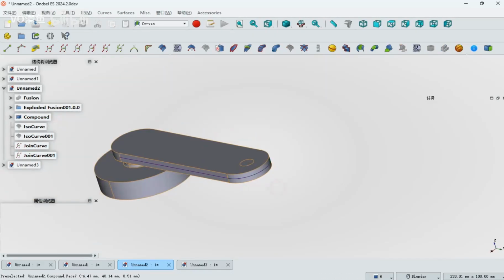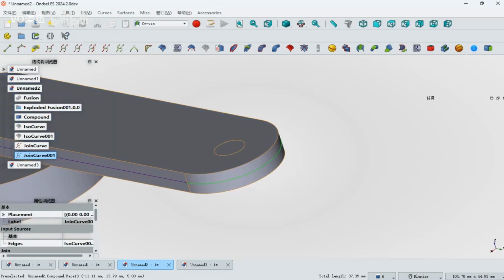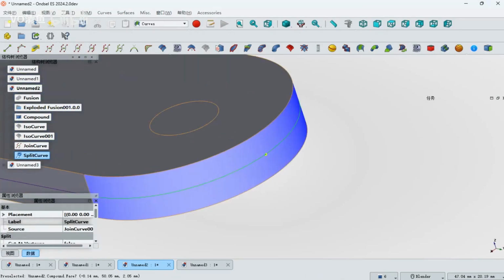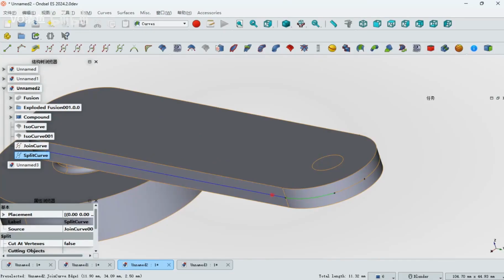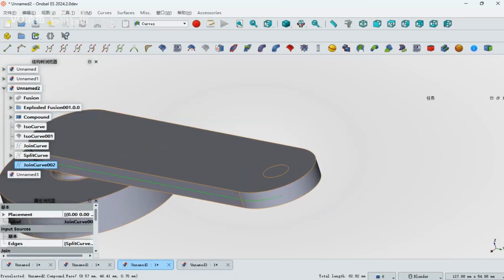For example, in this fillet area, I only want to keep a specific section. Let's say up to this point here. We only want this portion of the loop. So for this half loop, we take the current curve object and enable trimming using the split curve tool. Then we select this section to trim. For instance, we trim it at this location. After trimming here, these two line segments are extracted separately once more. This curve here is what we have after the isolated extraction.